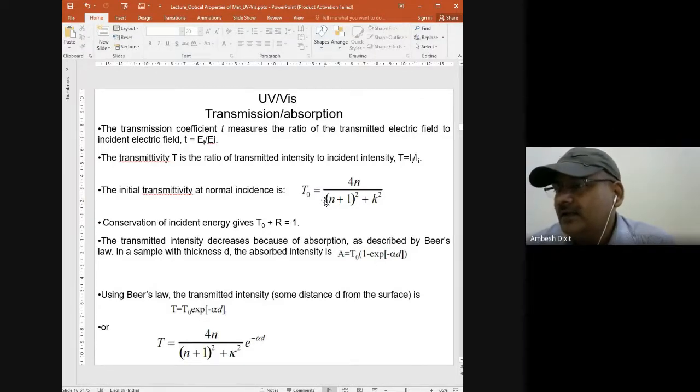Then alpha, absorptivity, is still a function of lambda, but it is defined as the integration from lambda 1 to lambda 2 of alpha lambda, that is absorptance, d lambda, normalized with respect to the black body radiation, the integral from lambda 1 to lambda 2 of the corresponding black body radiation d lambda, right?